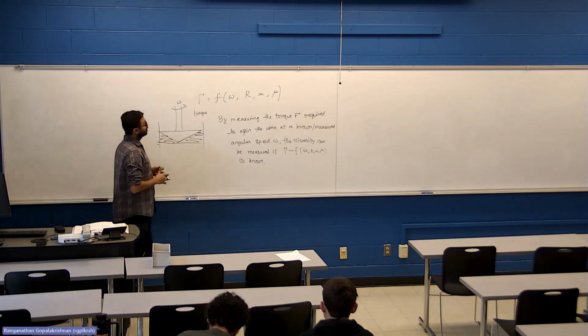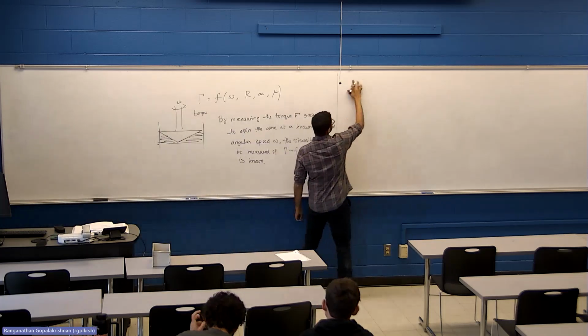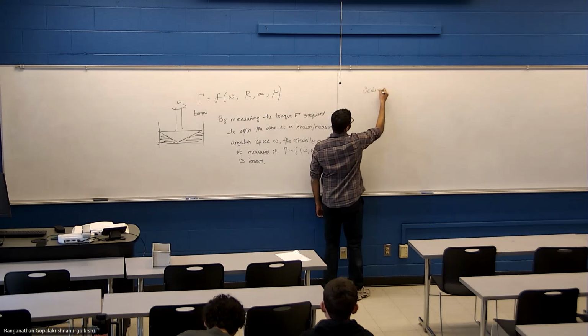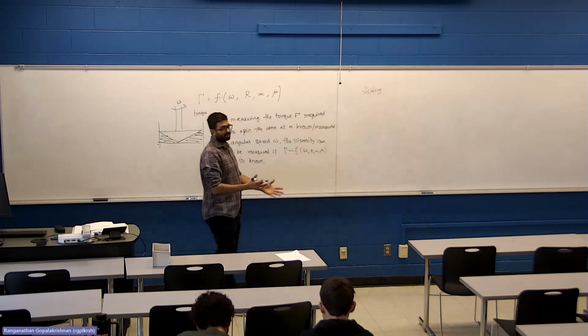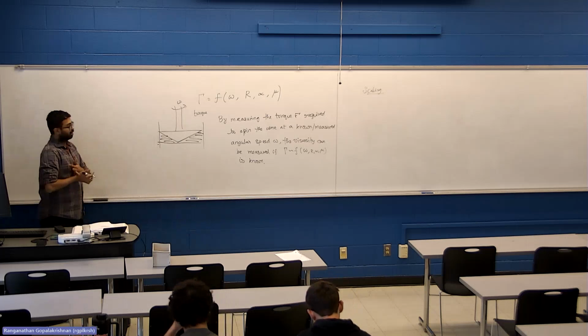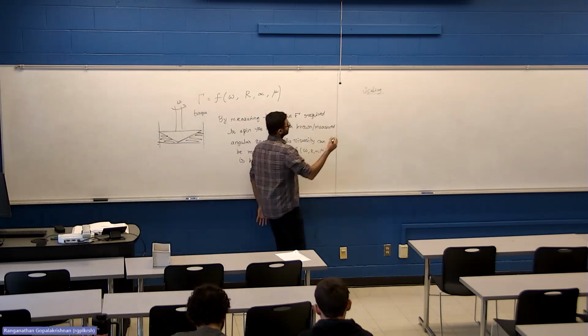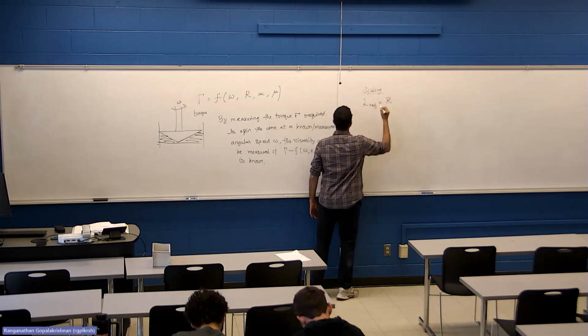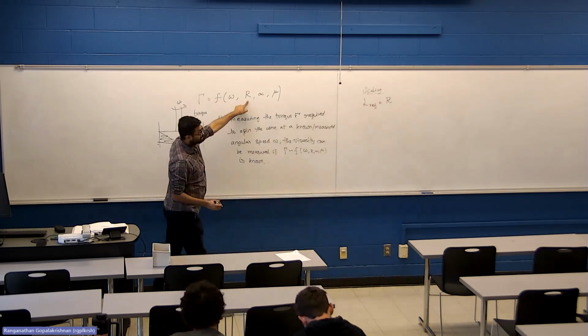So first thing we want to do is to express this in scaling in non-dimensional form. How to do the scaling? This is your exam problem. What's your first step? Choose a reference length. We need to choose a reference length, which obviously can be the radius because it's the only length present.